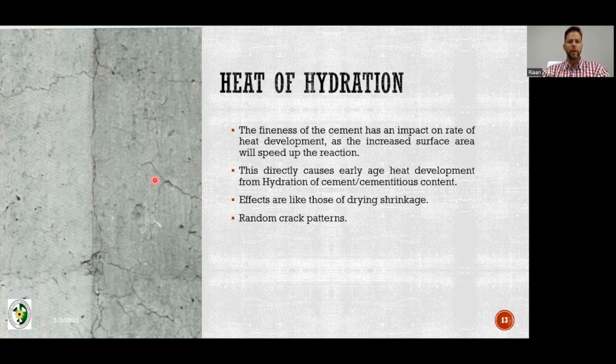Yeah, we had a case, a gentleman that attended one of our courses. They were doing a base for a mine, a fan base, and I think the base measured something like 4 meters, 2 meters, 5 meters, the 3 dimensions. And he noticed a crack along the middle of this base. Initially, that was the only crack he noticed, and he took pictures. This was 2 days after the cast. He then went and asked, listen, did you guys check heat of hydration on this? Heat of what? So that answered his question.